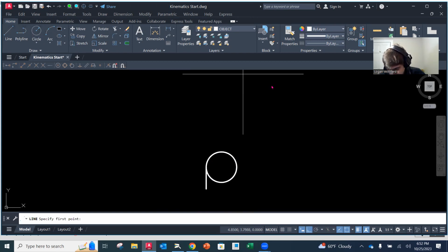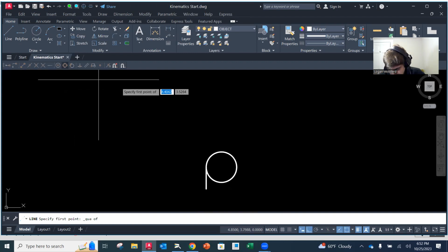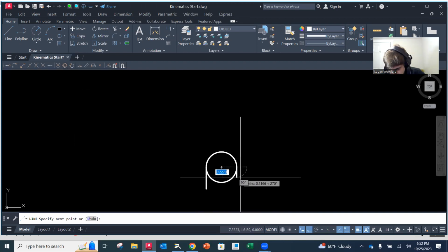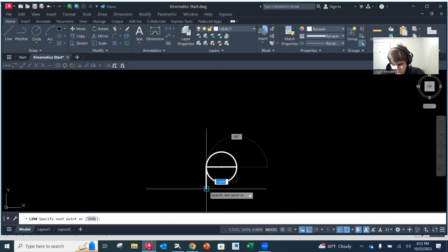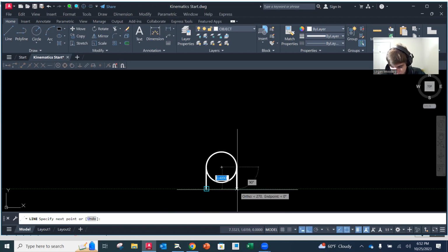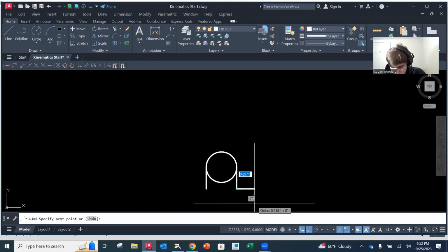Then I'm going to do the same thing on the right-hand side. Quadrant, oh, it doesn't grab it. So I'm going to hit that quadrant up here on my toolbar. Click there, go straight down. Now I want it to be in line with. So if I activate that point on the bottom there, your snap to lines should be again a default. Do you guys get that? Okay, so you can click when you get down there and then escape to be done.